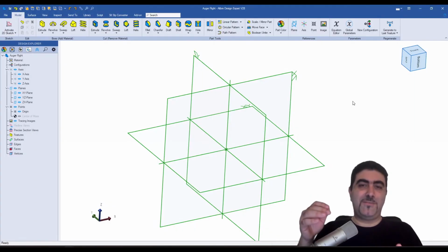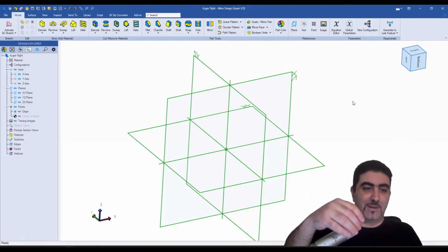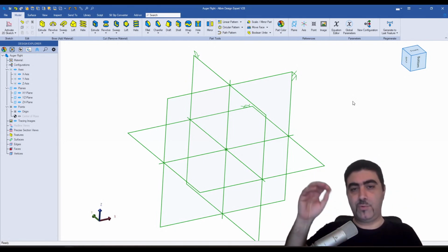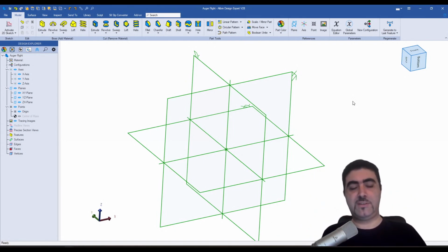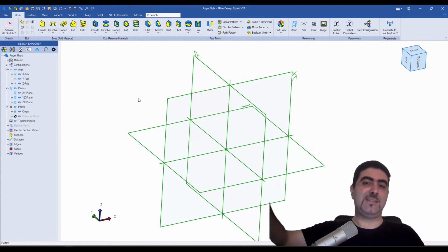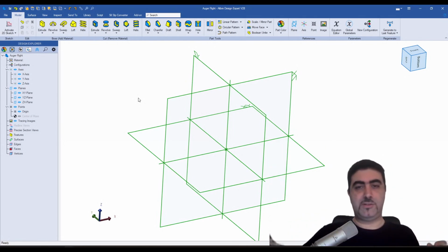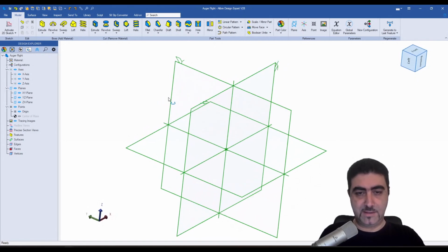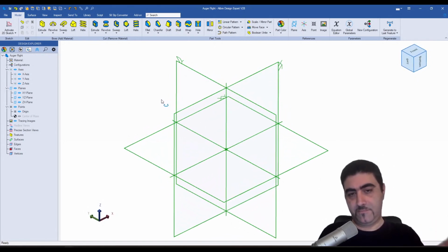The flights of an Auger are all cut individually, and then they're stretched, and then they're welded onto the Auger shaft, and that's how you create your Auger. To my knowledge, there's not a way to manufacture a continuous helix that you then fit over the shaft and weld. At least not an economically viable one.